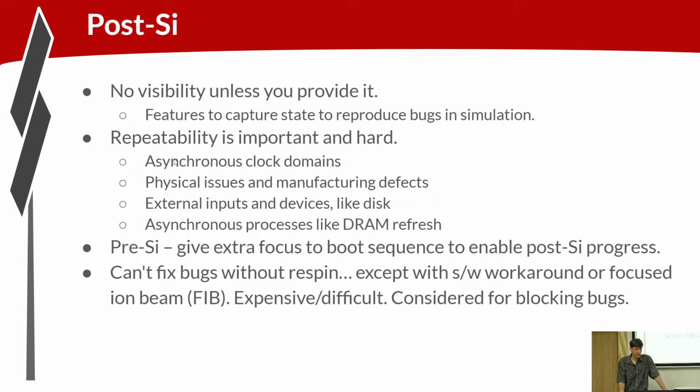So, the asynchronous nature of those domains is certainly a consideration for the post-silicon work. Physical issues and manufacturing defects, right? These are by nature hard to predict. If your silicon is just not reliable, you have a bit of memory that you can't trust to actually hold a one. Sometimes it might work, sometimes it might not. It's hard to reproduce.